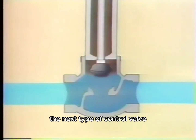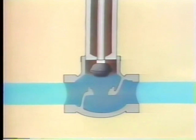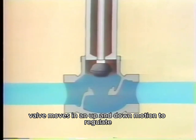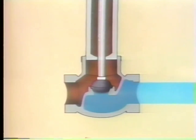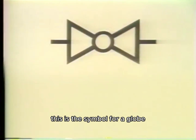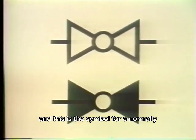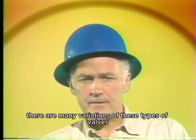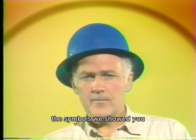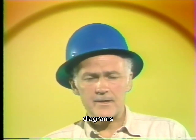The next type of control valve we'll discuss is a globe valve. The disc in this valve moves in an up and down motion to regulate or stop flow through the valve. This is the symbol for a globe valve in a normally open position. And this is the symbol for a normally closed globe valve. Remember, there are many variations of these types of valves. The symbols we showed you are commonly used to represent them on plant system diagrams.